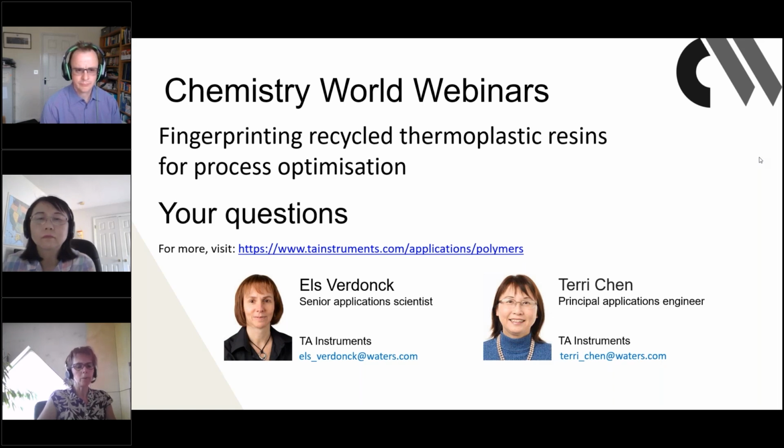But more often, people will use a more complex method, and instead of only looking at the peak maximum of the crystallization, they will look at the full exotherm of the crystallization and make partial area integrations to get information about how much material is crystallized after a certain time. And then they will fit the full information to different kinds of models. One example is the Shestak-Berggren model, but people also are using the Malkin model or the Avrami model.